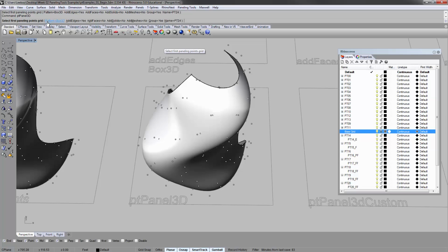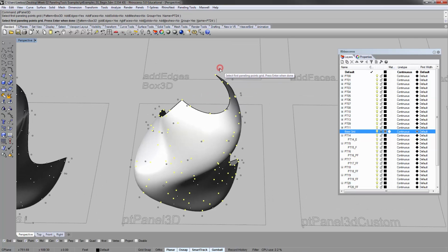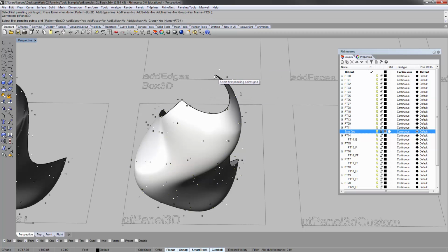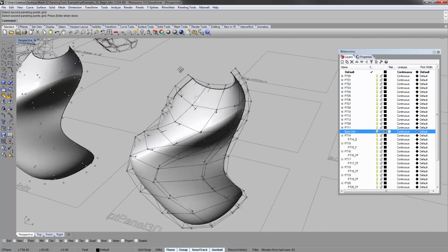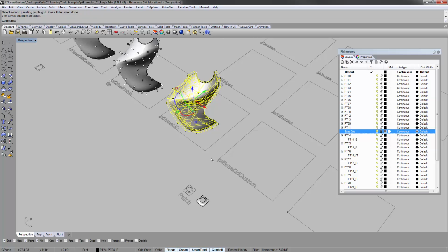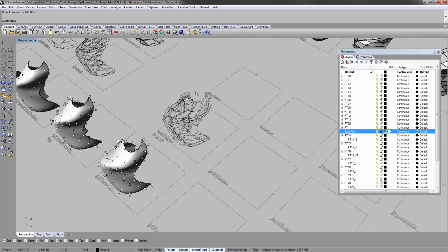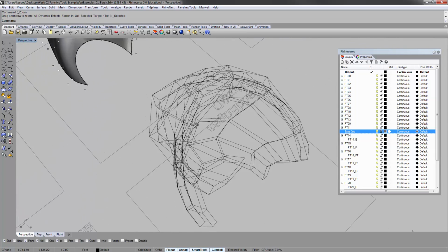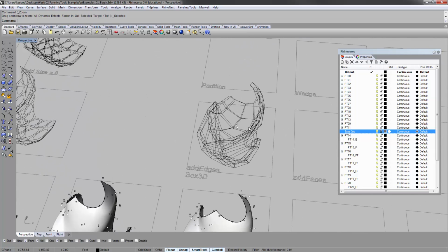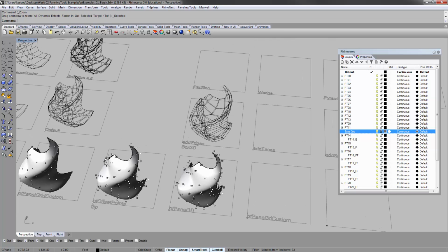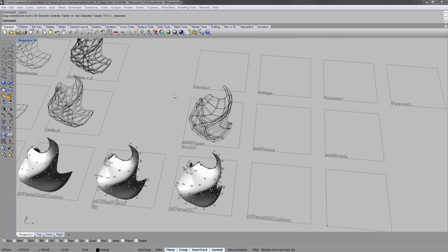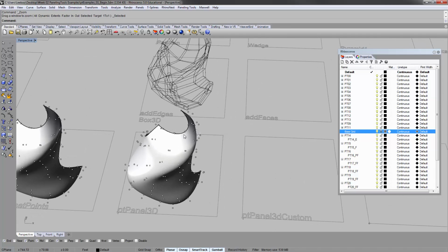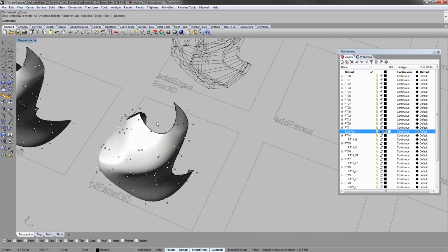So let's run the command again. So pattern box 3D with edges and nothing else, grouping it. First grid inside, second grid outside. Oops. First grid inside, enter. Second grid outside, enter. Okay. So that actually gives you the thickened, basically, wireframe. Same thing, edges. And I'm going to go through and put in all the options, which you should try on your own as well.